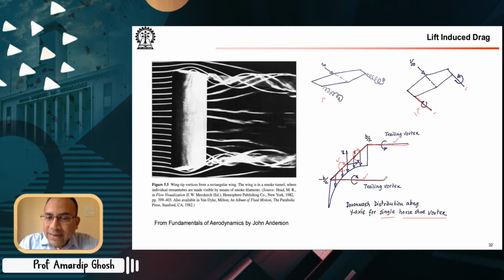And the vortex lines are aligned with them. Okay, so that's why we get a straight vortex tube or vortex filament. So nonetheless, the strength of the bound vortex here and the strength of the vortex filament on this side will be the same. Okay, that will be as per the divergencelessness of the vorticity field.